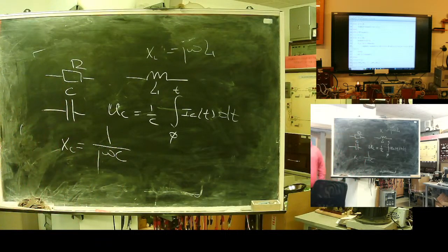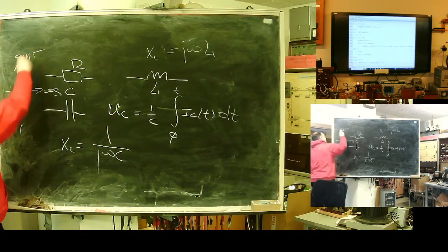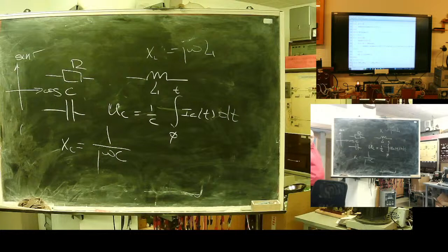If you take an integral of sine, you will get minus cosine. Means rotation by 90 degrees. Which way? Forward. One more time: cosine, sine. Voltage is sine omega t. If voltage is here, minus cosine will be here. You need to go forward.